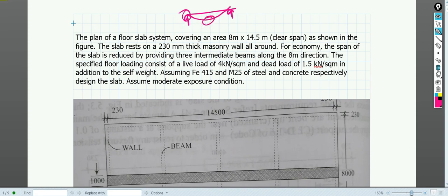But in reality, in most slab-beam frame systems, or in normal regular structures, you will see that the slabs are monolithically cast with the beams, and you will not find that it is simply supported, except for, suppose, bridges and all. In a normal building, you can see that beams are monolithically cast with the column. So there is nothing like simply supported beams in regular structures.